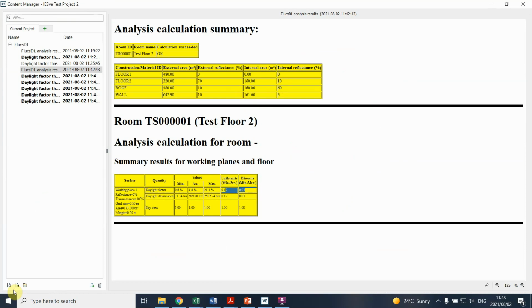There's something else that we also assessed, and that's the illuminance, which I think is important. If you look down here, it says, remember, the illuminance is now at 850 mm above the finished floor level. The minimum illuminance is 71. Now you can go and look at SANS. There is a SANS standard for that specifically. I'll share the note with you. I believe it's section O from 10400, but there should be another SANS. It's also very, very specific.